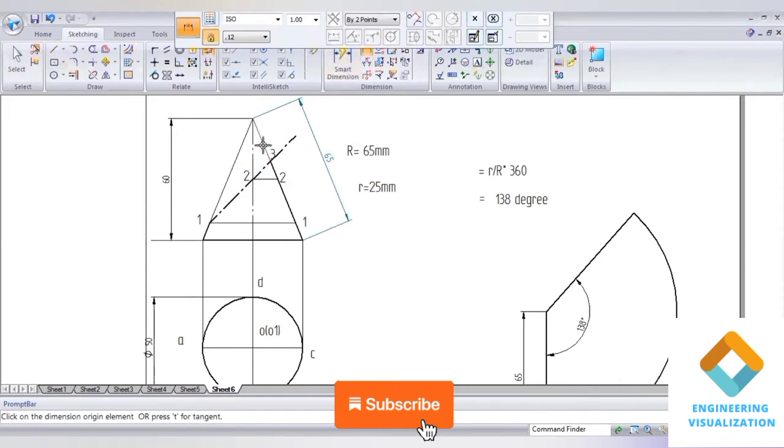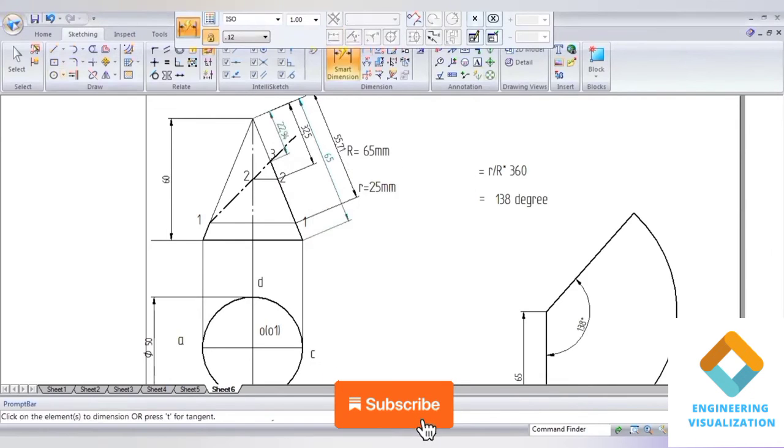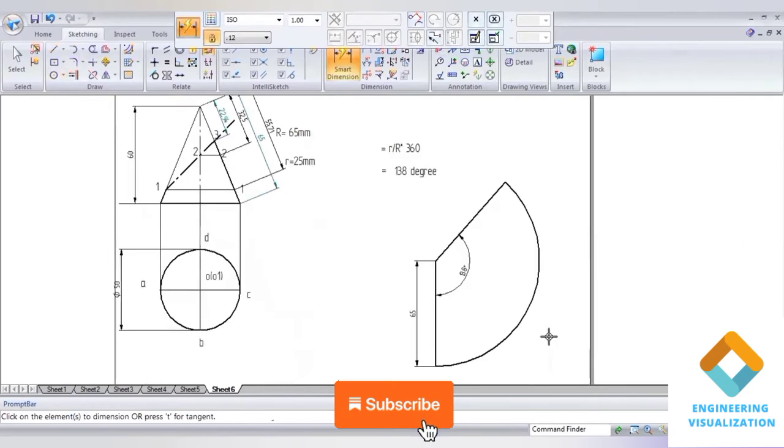So we can measure the dimensions here from that exact apex point to here, that is 55.71. Then from that apex point to the point number 2, we can measure the dimension. That exact length we should measure using distance between 2 points. You can change that option here, and then you are able to measure the exact points. Okay, this is what the dimensions we get: 55.71, 32.5, 22.94.